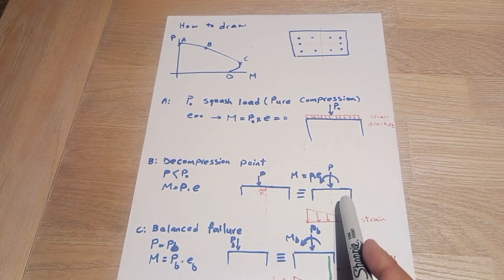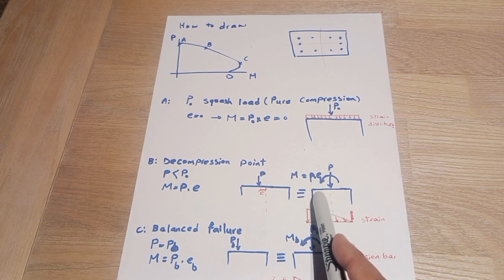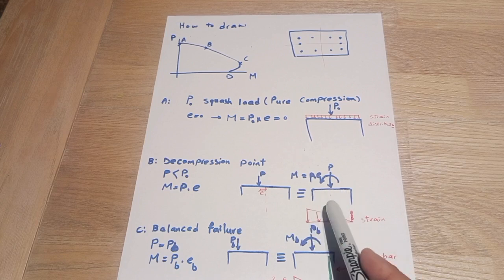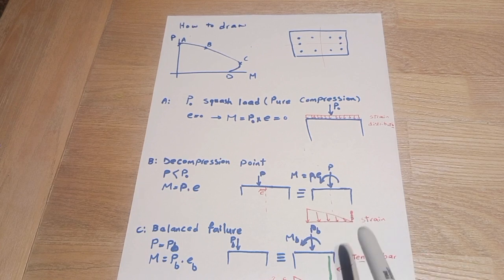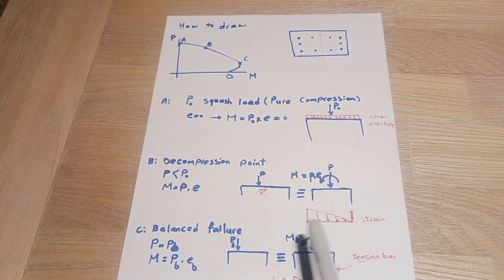It means that still on this area, still on the other area, all are in compression, and concrete is completely under compression. But the extreme point for tension is zero strain. It means that it is going to the tension zone, but it is still under compression. This is the strain distribution starting from 0 to maximum for concrete, that is 0.003 in general.